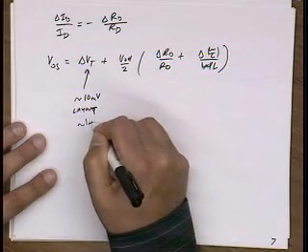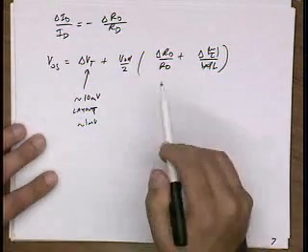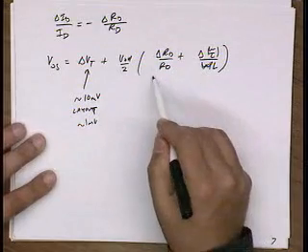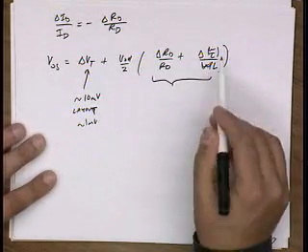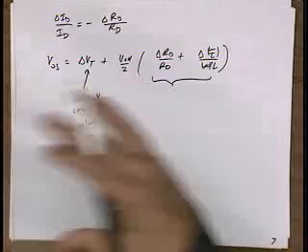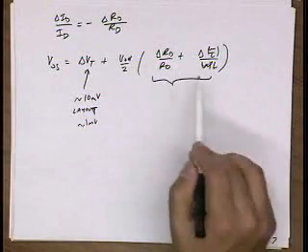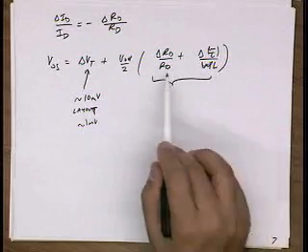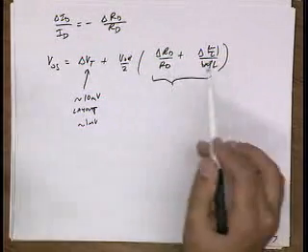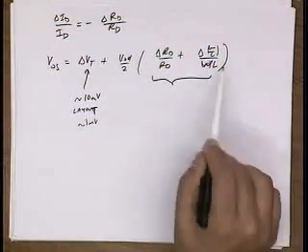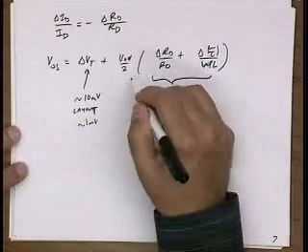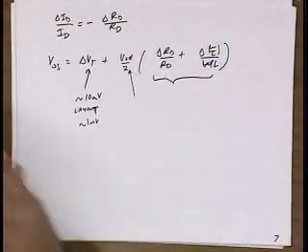Good design, you can get it down to millivolt, sub-millivolt. This term is almost identical, right? Instead of delta IS, I have this delta W over L, which also carries all that baggage with it. Let's say I can get the same precision here. So this works out to, let's say, 4 or 5%, this parentheses.